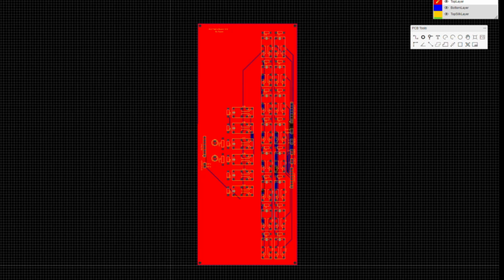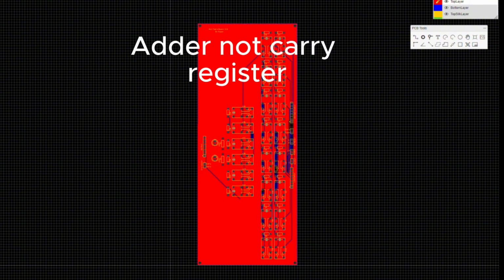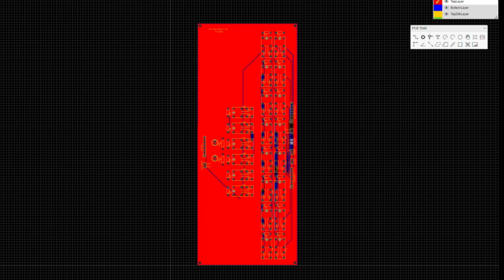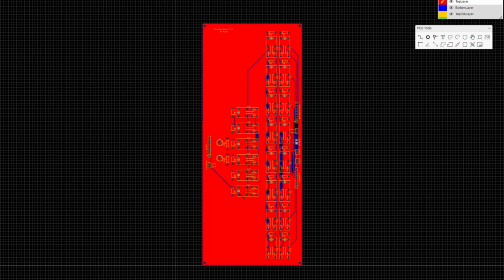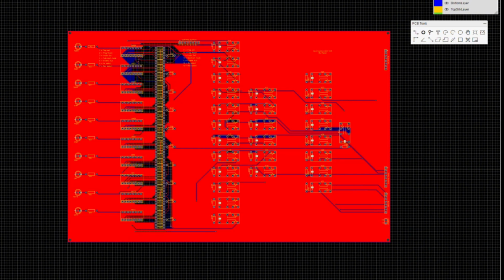It gets outputted next to the bus, and the carry flag comes in from the carry register, and you set the flags using the set and reset. Now you must always reset before you can set it, or otherwise it will basically do an AND, and that's how this one works. And you have your LEDs here to show you the current status of the flags, and that's everything.